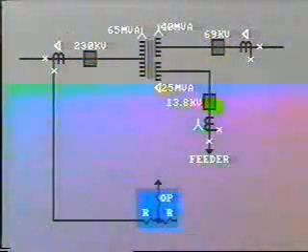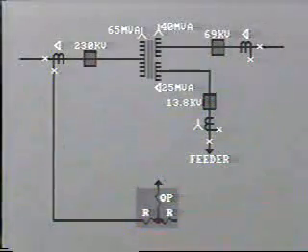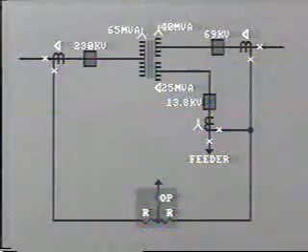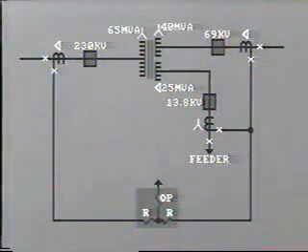How would we handle this transformer differential protection if the differential relay had only 2 restraint coils per phase, like this? In this case, we would have to parallel the CT from the third winding with that of the second. As long as the load in and out on all 3 windings balanced, this would be acceptable.